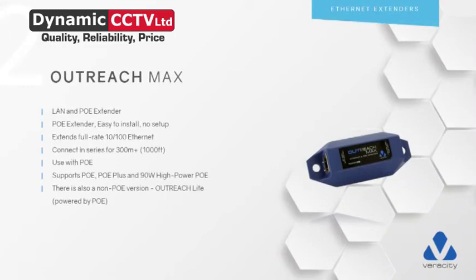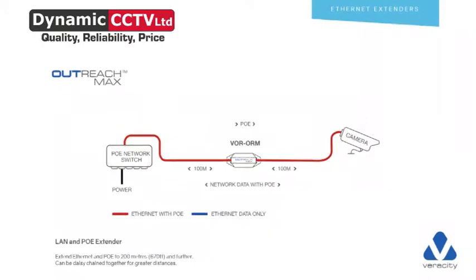You can series wire these as well, so you can have 1, 2, 3, 4, etc. If you're going to go that far, you're going to put 4 in. My recommendation is to use our long span, which I'm going to show you in a second, and you'll see the reason why, because again, that would save you money. The interesting thing about this product is the fact that this will carry high wattage. This will take 60 watts, and can carry that 60 watts up to 200 meters. Not a lot of products in the marketplace can do that right now, but this will. That's how it fits together.